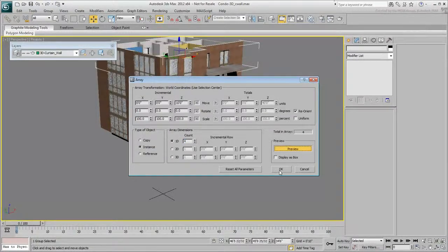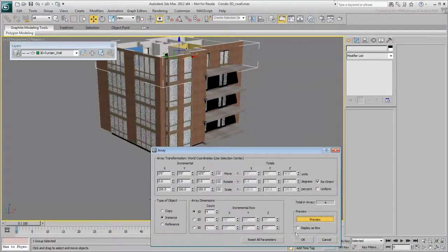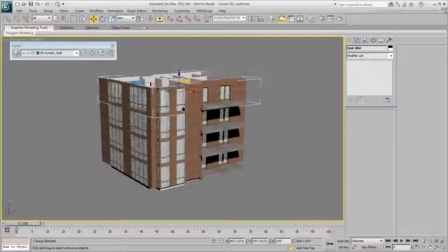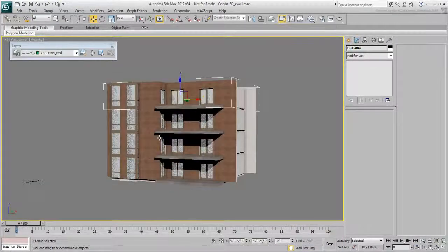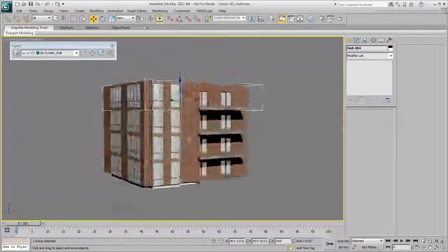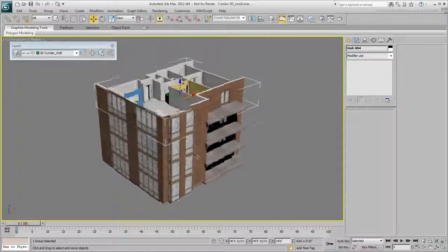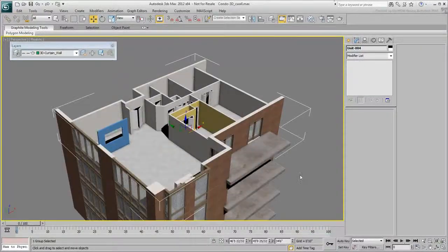In some cases, you use built-in tools like simple wall extrusions and 3D doors. In other cases, you learn to use polygon modeling techniques to fine-tune the work like bridging gaps and building curtain walls. You have also learned about the importance of multi-sub-object materials and how to manage them. Let us know if you have enjoyed this tutorial.